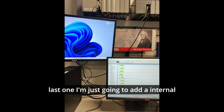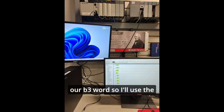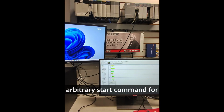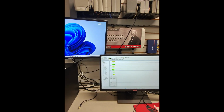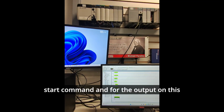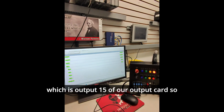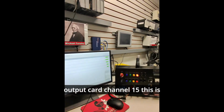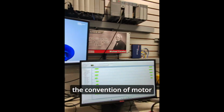And then for our last one, I'm just going to add an internal bit, which is going to be our B3 word. I'll use the first bit, and this is just going to be an arbitrary start command for motor 2. So we'll call it MTR2 start command. For the output on this rung, we're going to address that to our second motor, which is output 15 of our output card. So again, slot 2 for the output card, channel 15. This is motor 2. We'll call this MTR2 to match the convention of motor 1.